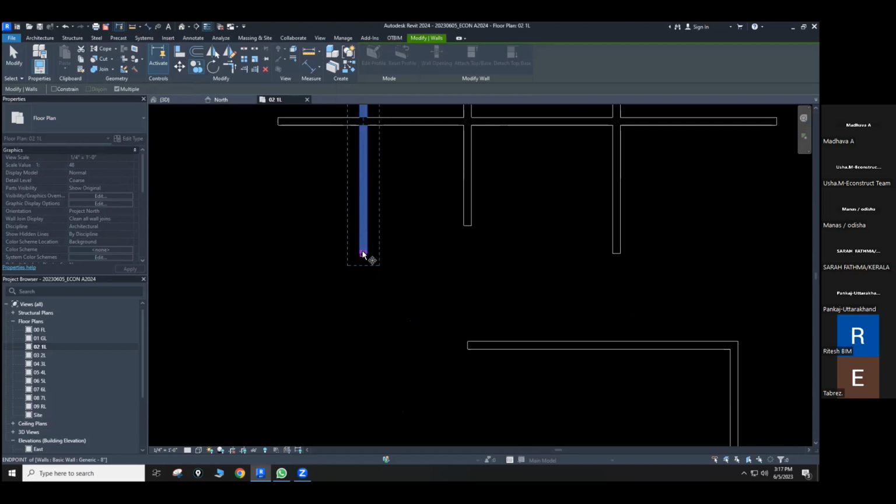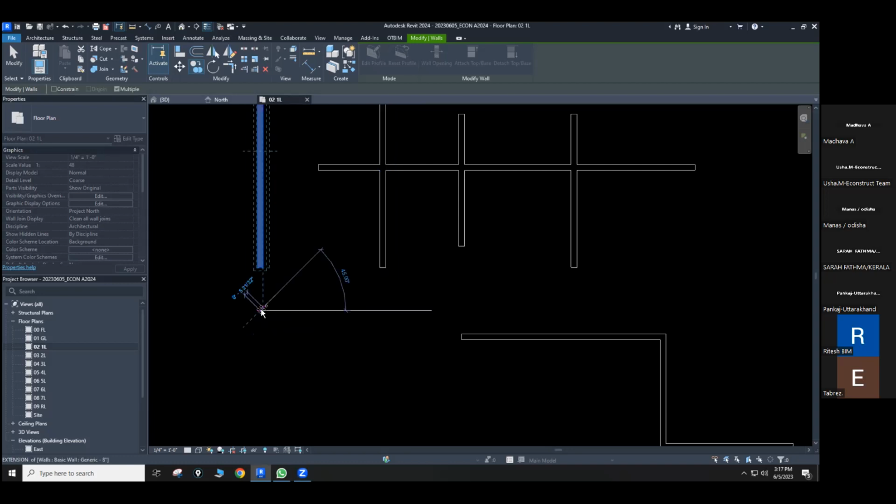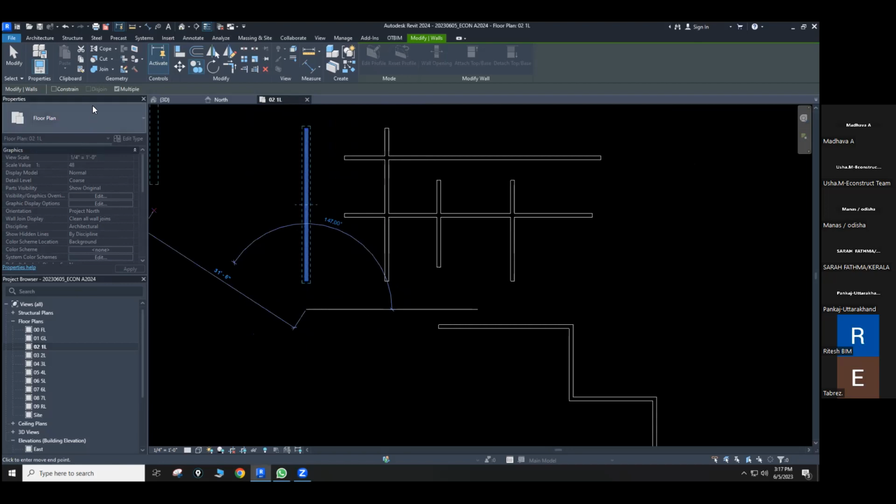You can also click the center point, or use a constraint and click outside. Where I need to place it, I just follow the dimension. The dimension showing in bluish dotted color is called the dimension constraint. It shows 15 feet or 14 feet. You can click it here and continue to click, because the command's multiple option is activated here.